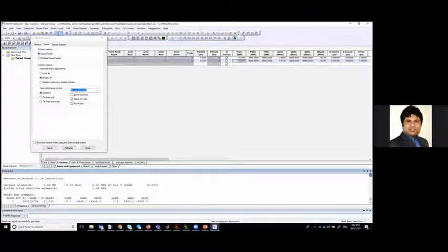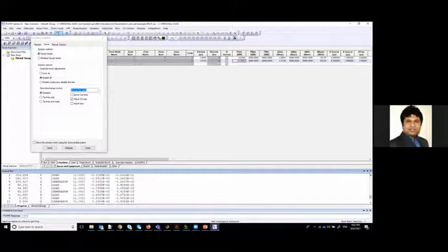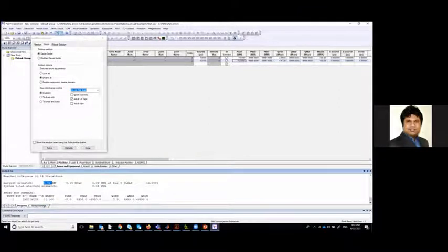If you look at the output, it shows a lot of different things, but at the end, in the summary in the output bar, it says the solution met tolerance in 14 iterations. The largest mismatch is 0.2 in the active power mismatch, so there is some error showing. The largest total system mismatch is 0.04 MVA, which is not much. This is the solution meeting tolerance.